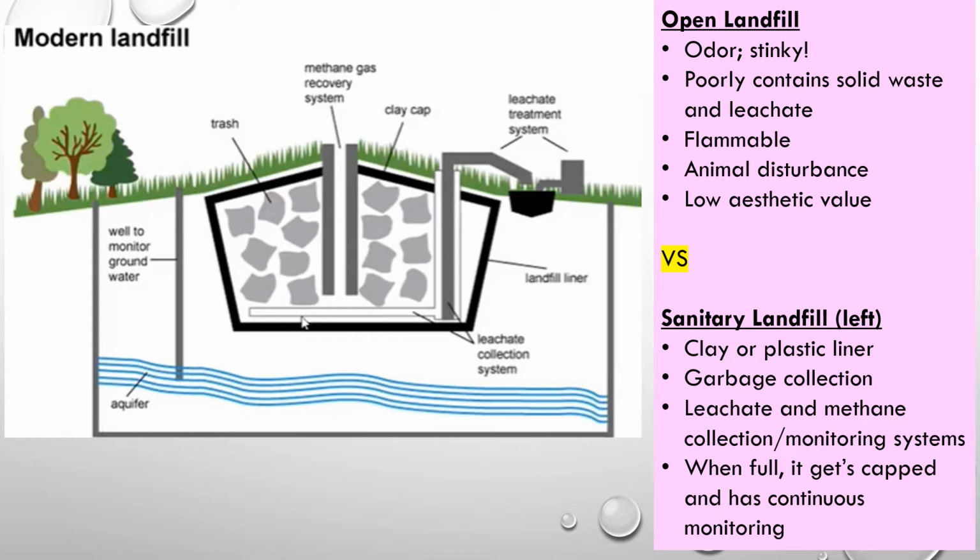A sanitary municipal landfill consists of a bottom liner, which is mostly made of plastic or clay or both, and that's what I'm following here with the laser pointer. So that's your liner. Then a stormwater collection system, for if it rains or water gets in here from any kind of muck, that it has to be collected into a water system. This is also where our leachate goes, which is the water that leaches toxic material and other chemicals out of all the trash. And then a cap.